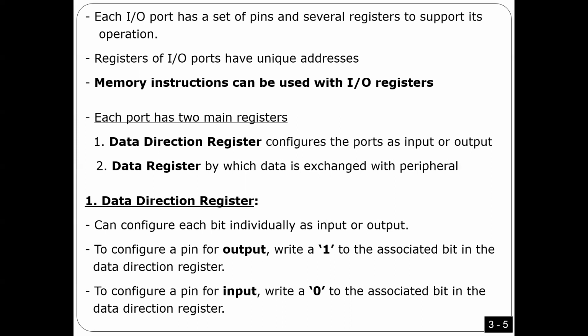If it is input, so this pin, we have pins here. This is connected to the data register here. Again, every pin should have a bit here. So on this pin, if I put 5 volt here in this pin, it automatically is going to be logic 1, right? And all you need is just to read it to see if it is 1 or 0. You got what I'm saying? Here, if you put 0 volt, so 0 volt is going to come to here, and then you have to check this bit. You understand what I'm saying, guys?